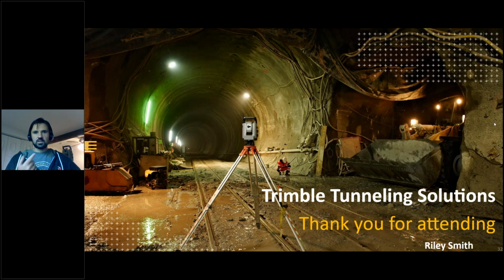There's one that's related that I just saw come up here about testing the breakthrough precision. For anyone who's not familiar, breakthrough is essentially if you have two tunnels, or you have one tunnel and you're constructing from both sides, so you have two machines working towards meeting in the middle somewhere. You have what's called a break point, and that's the point at which those two traverses are going to line up. It's never going to be zero, so you have some type of tolerance which you're trying to meet.